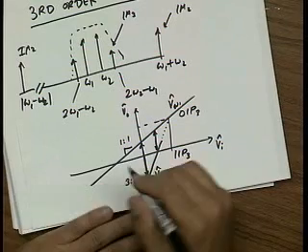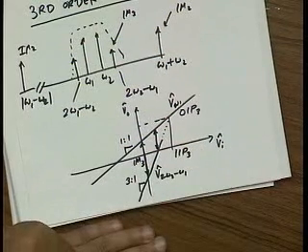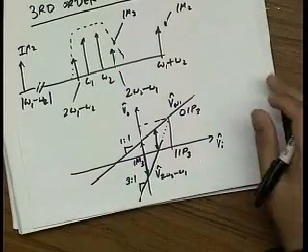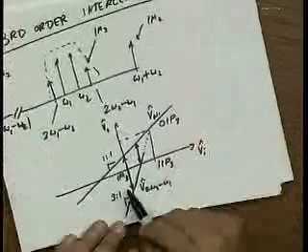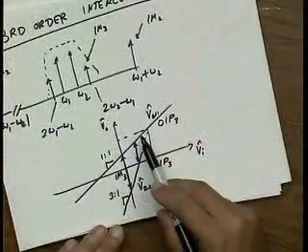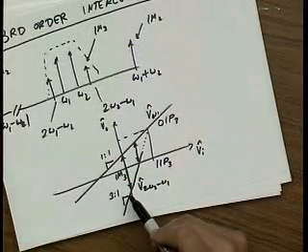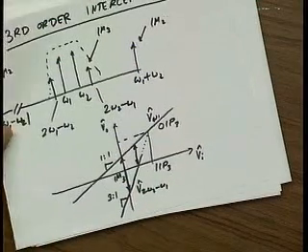Questions? Comments? All right, so what we're going to find today is, yes, there's a question. IM3 is 3/4 of the input squared. So where did the cube term come from? So why is it cube? Am I missing something? Let me actually solve the equations and we can see where that comes from. Okay, let me answer your question. It's actually quite simple. Look, IM3 is increasing like the square, but the intermodulation is increasing by the cube. Does that make sense? Okay. Very good question.